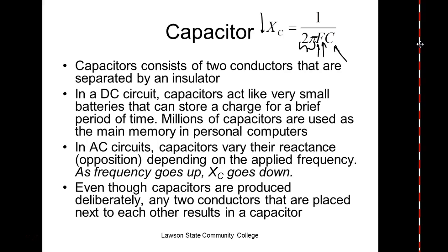The problem we have with that though is capacitors and inductors vary with temperature. I don't know if you remember that, but you used to have a fine tune on your radio and your TVs. You'd listen to it a little while and then it would go out and you'd turn the little fine tune and you'd pick it back up, because your capacitors or your inductors were changing with temperature.